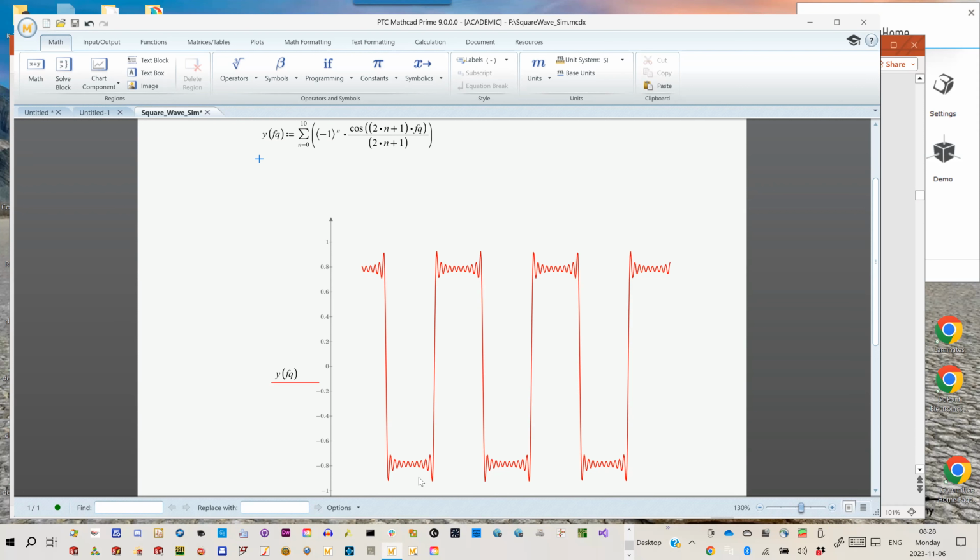Now, this is the point that I want to get across to you guys when it comes to these square waves. The frequency that you run your clock at, and we're going to talk about this here in a minute, your clock frequency has almost nothing whatsoever to do with your signal integrity. I have heard over and over again engineers tell me I don't have to worry about signal integrity because my fastest clock speed is only 100 kilohertz. It's ridiculously slow. And I said, yes, but what is the rise time? And the reason being is it's the rise time of the chips.